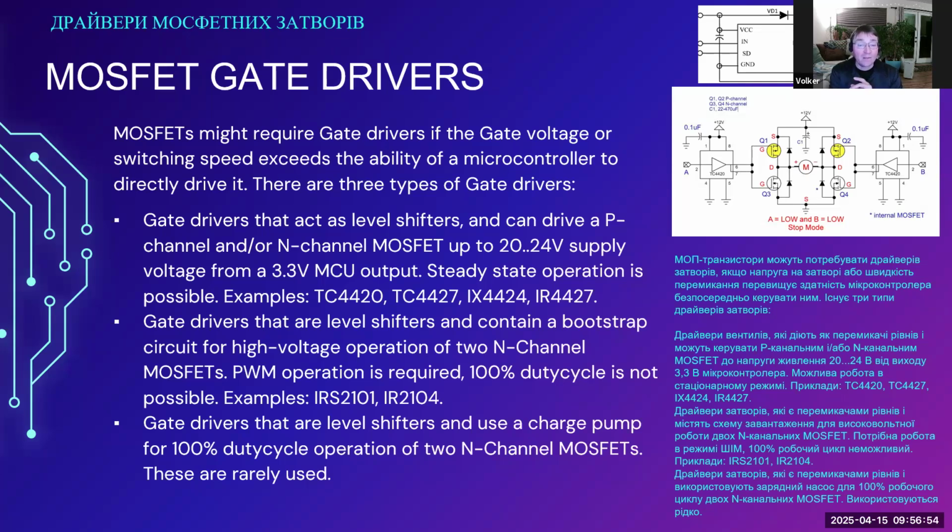So these MOSFET drivers usually come in a SOIC 8 package, some in a SOIC 16 package, some in a smaller package if it's just a single gate driver. But the ones that I've listed here come in an SOIC 8-pin package. They come from a line of gate drivers that all do the same thing, with slight differences: some are inverting, some are not inverting.